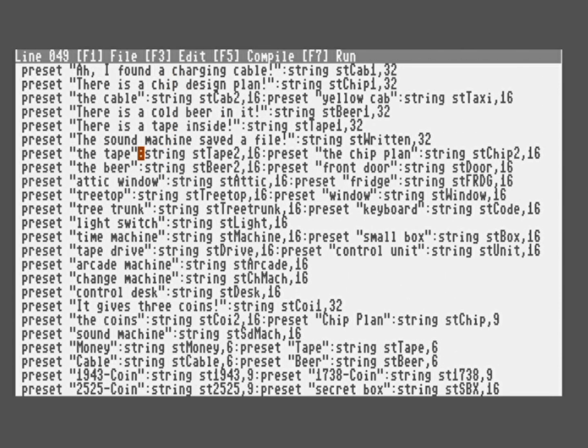Maybe one thing about this preset directive. This means that the specified value is written to the memory locations when the variable is created, and there is no need for a runtime function to assign the value to the memory locations, and this simply saves memory.